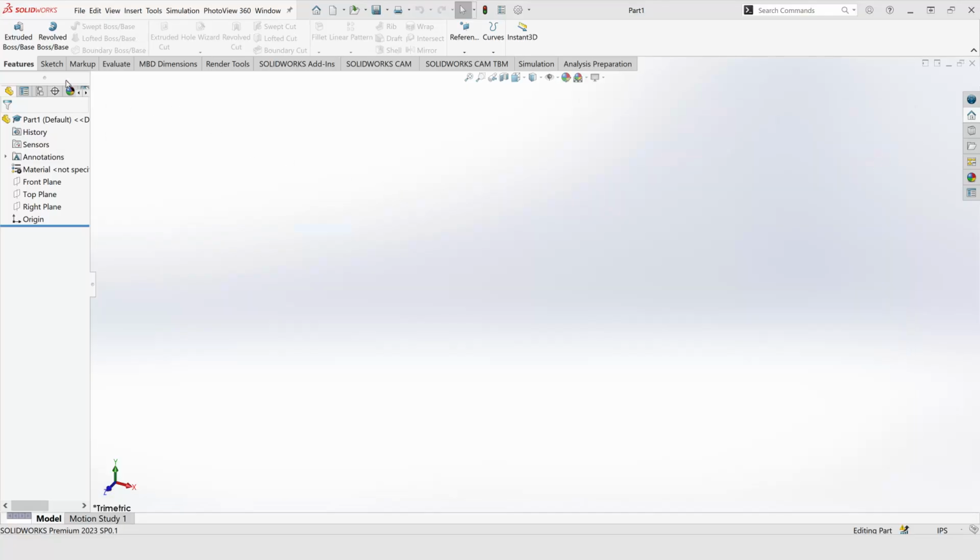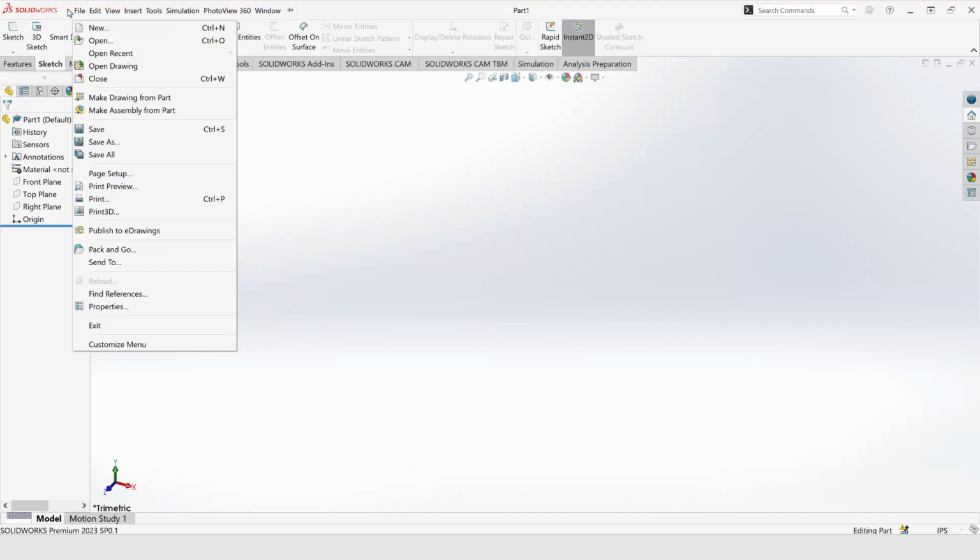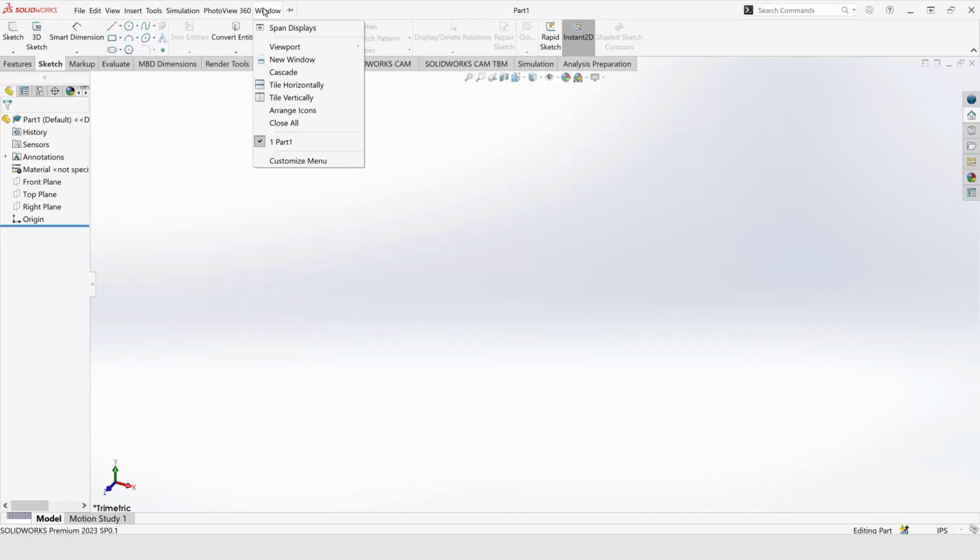So what does it mean, Sketch tab? I'm going to click on the tab that says Sketch, and there's my circle. So those are the two circles that it mentioned. And then the pull down window is here. Yours is probably hidden. Next to the SOLIDWORKS name, you'll see a little triangle. If you hover over that triangle, it's going to open up all these options.